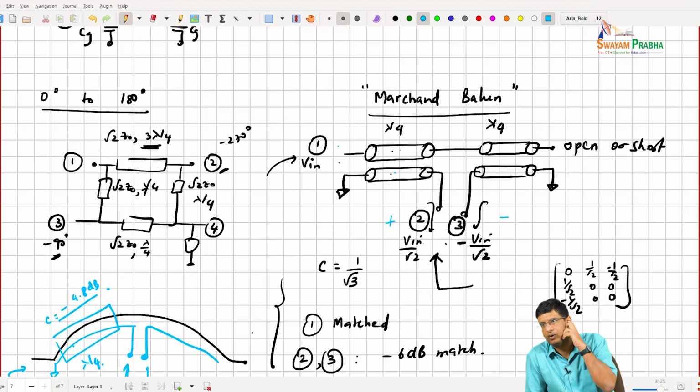So it can also work as a differential power combiner, which can be a useful circuit in many applications. So we have built quadrature dividers and combiners, in-phase dividers and combiners, anti-phase dividers and combiners. So we are now able to use these building blocks to start building phased arrays. So next we will look at phased array architectures, and then we'll talk about phase shifters and attenuators today. Okay.